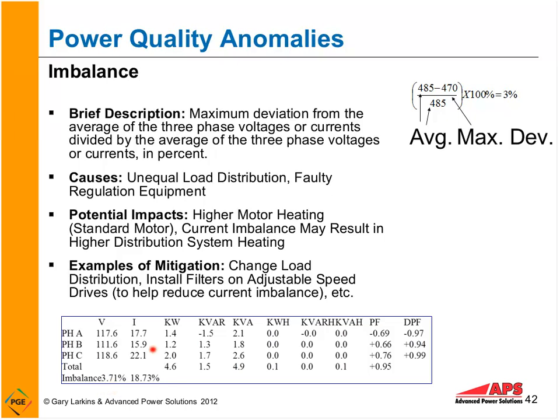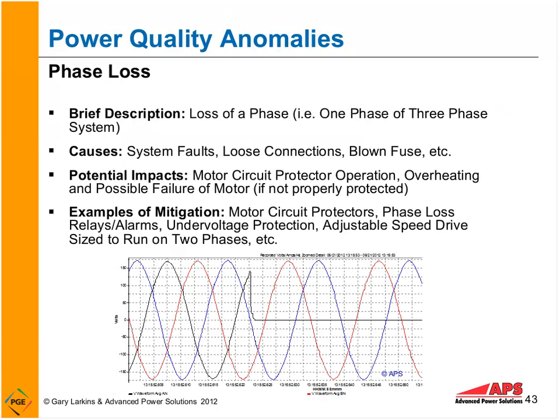And we can see the load here is not evenly distributed from the current flow between the 3 phases, causing extra loading on phase 2. Phase loss. Here we have an example of we've lost a phase.